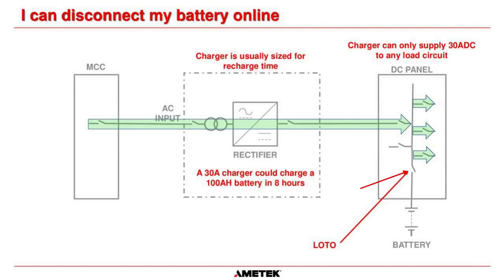They then decided we need that battery to be recharged within 8 hours. What size charger do we need to recharge those batteries? They did their calculations and said, to get the batteries fully charged, more like 90% charged in 8 hours, a 30 amp charger would be suitable. Obviously, they have to try and save cost. There's no point in putting in a 100 amp charger that's a lot more expensive when a 30 amp charger would do exactly what we require.